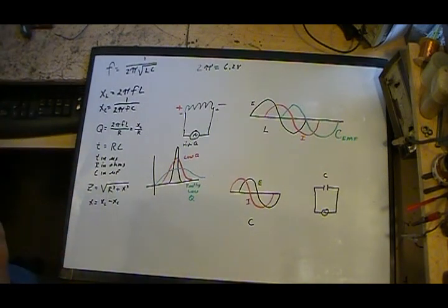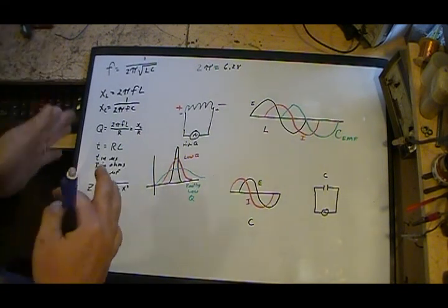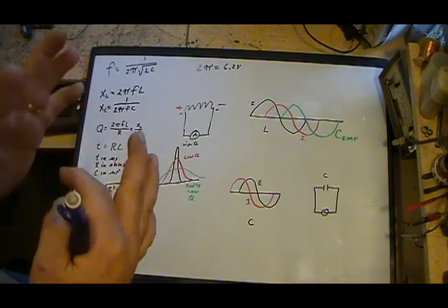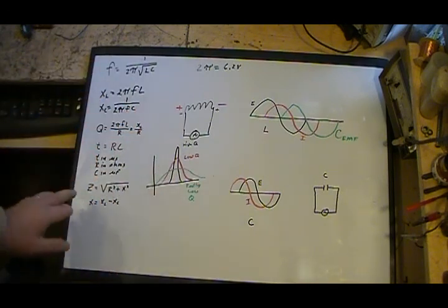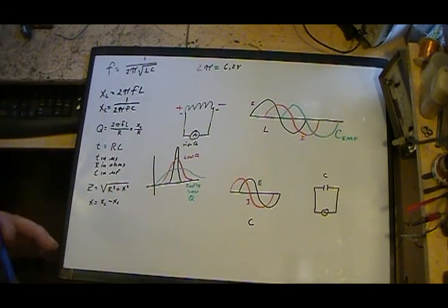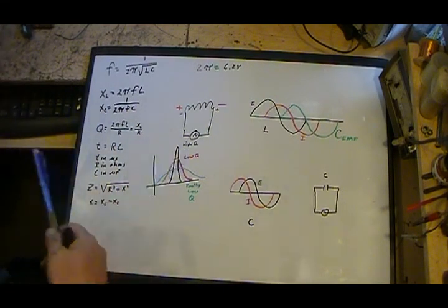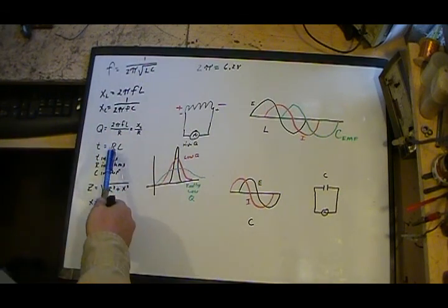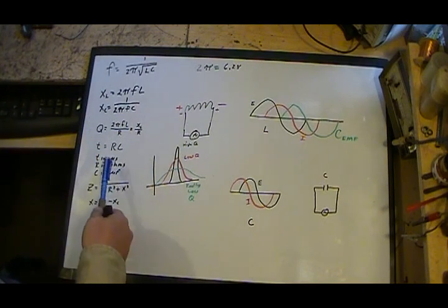You know how the volume goes up and down just a little bit in that audio, so you want to keep that so you can have good fidelity, but at the same time you want the AVC circuit to do what it's supposed to do. There are some design considerations, but that's where the time constant comes from.